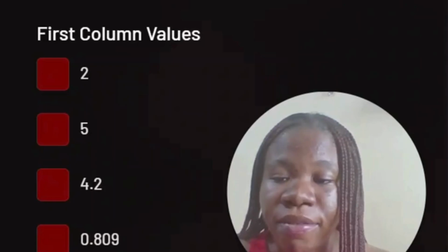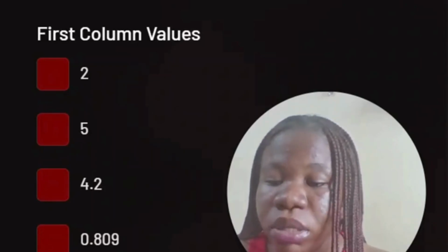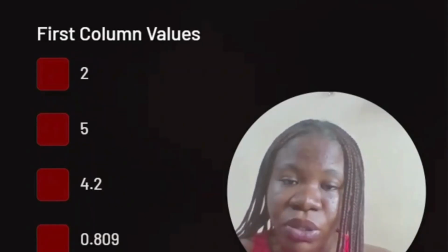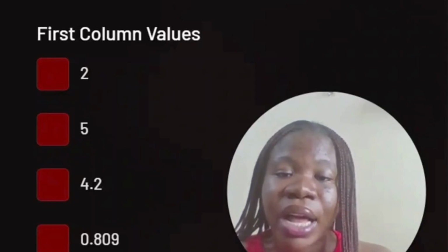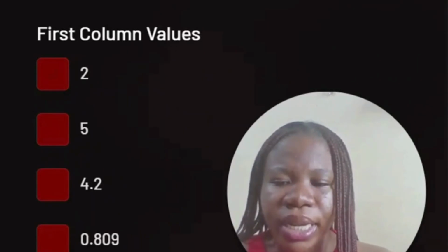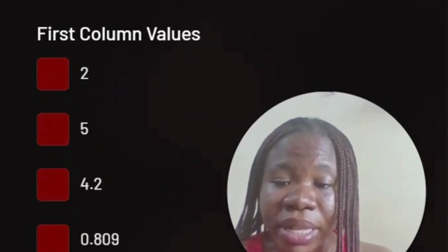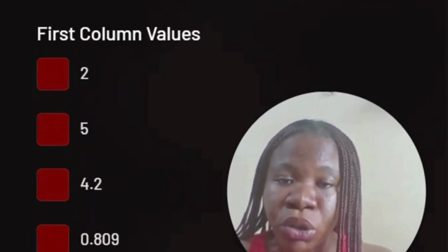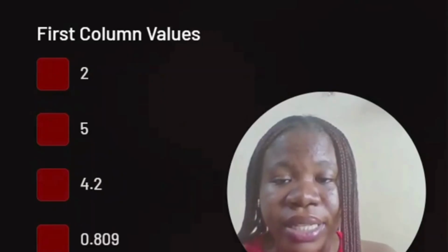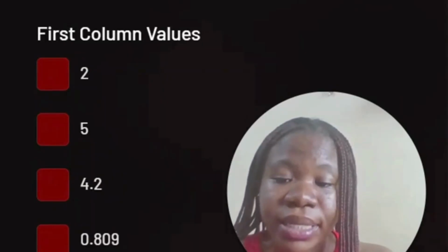So looking at our values, moving from the top to the bottom, all the values remain consistent in the positive range, meaning there are no sign changes whatsoever, which means that there are no poles in the right half of the S-plane. Why are we checking if there are poles in the right half of the S-plane? So in control systems, poles in the right half of the S-plane show instability, such that the system will grow uncontrollably over time, which we term as instability.